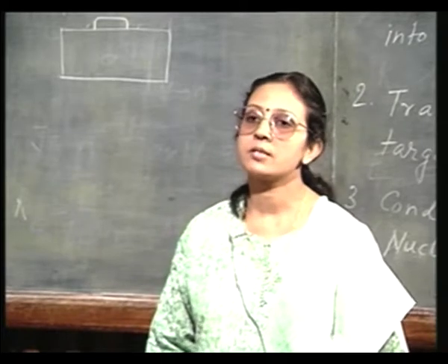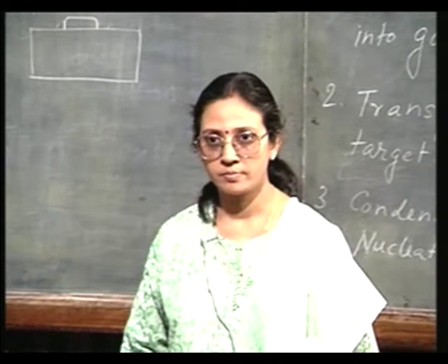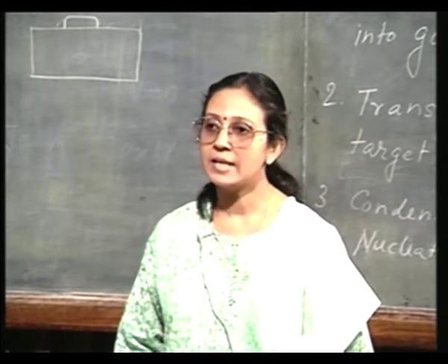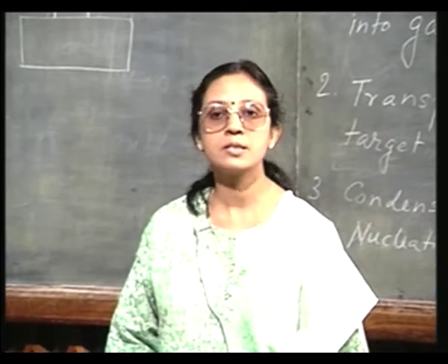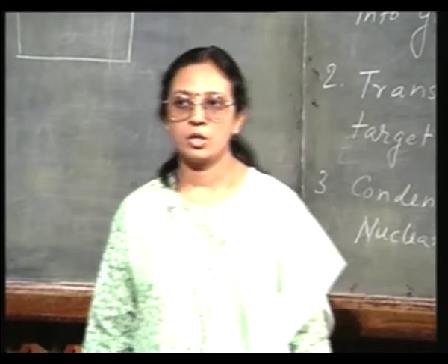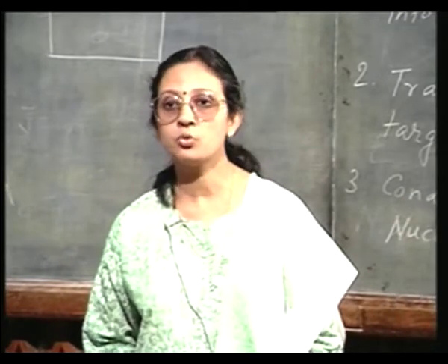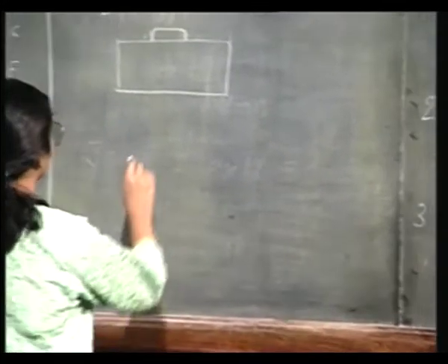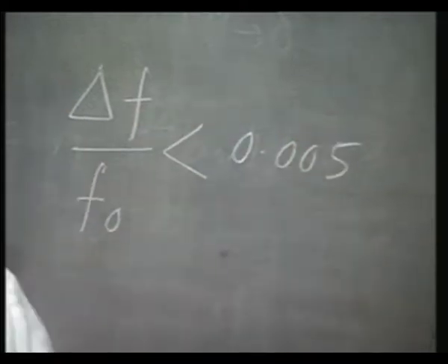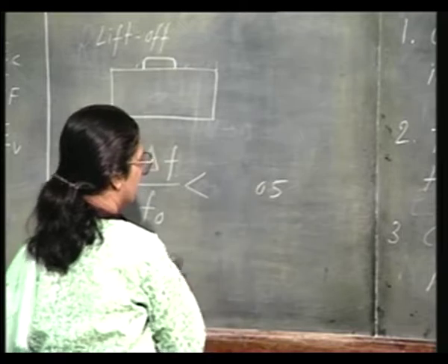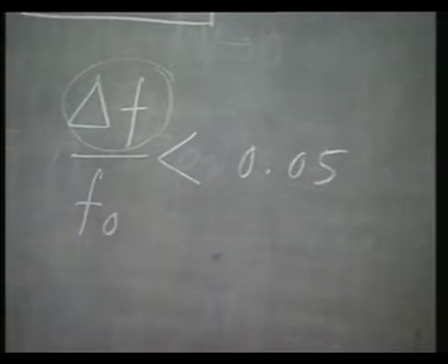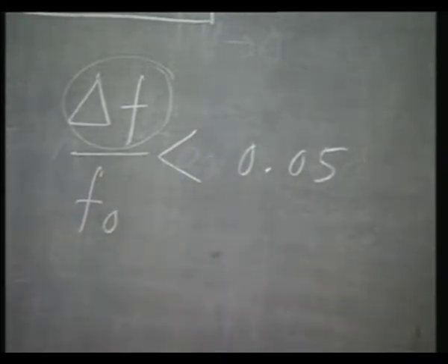If you keep the quartz crystal at the same level along with the substrate, then when metal film is getting deposited on the substrate, it is also getting deposited on the quartz crystal, and any film deposited on the quartz crystal will alter its resonance frequency, provided that the change in the resonant frequency delta f is very small compared to the original resonance frequency.